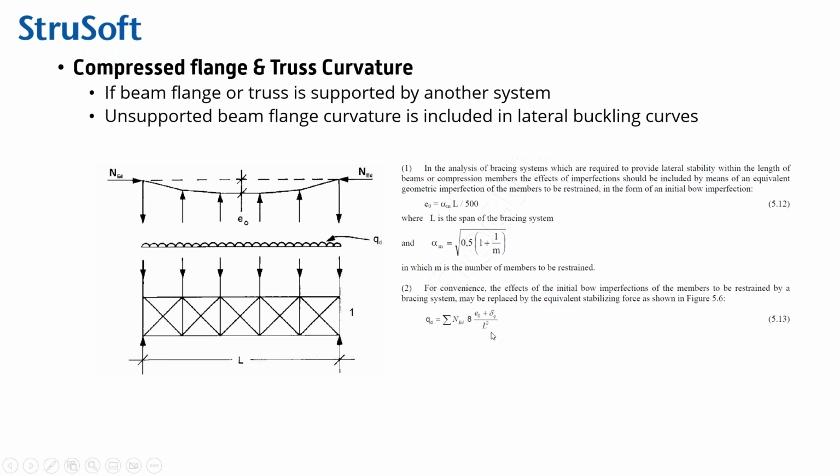So this means that this is actually an iterative process. What you have to do is first calculate this QD, the initial load to the bracing system. Then you look at how much it deviates, and if you have a connection on your bracing system, that also has to be taken into account. Then you apply this delta Q to this formula, calculate the structure, and again you get a larger QD because you have deformations.